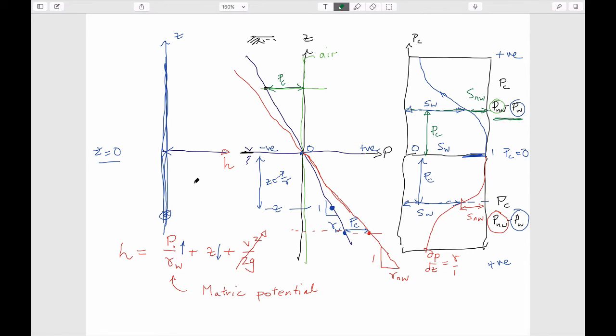So I guess the other thing that comes out of this is that if you drilled a hole in the ground and you measured at a couple of discrete locations what the pressures were at those two parts by using a piezometer, what would be the direction of flow that water would be moving in the aquifer? If you've taken 452, I bet you've talked about this. So if you drilled a hole to this depth here, you know the pressure is this magnitude, and you drilled a separate hole here, and the pressure is this magnitude. What's the flow? Can you calculate the flow velocity?